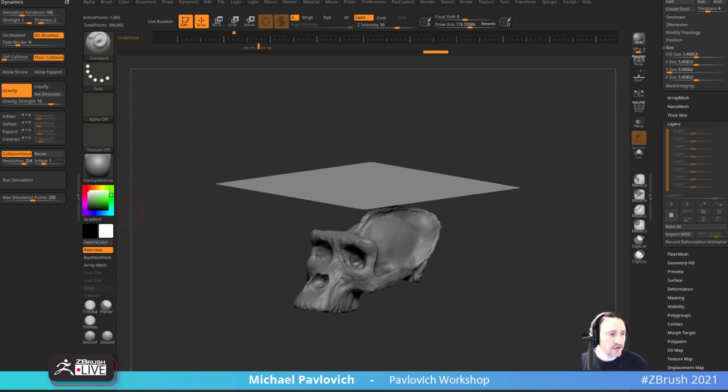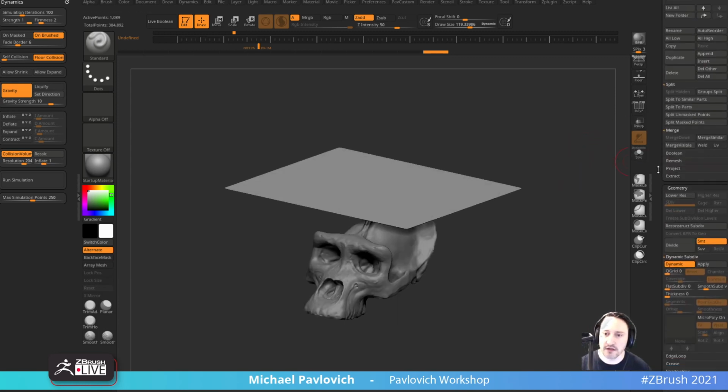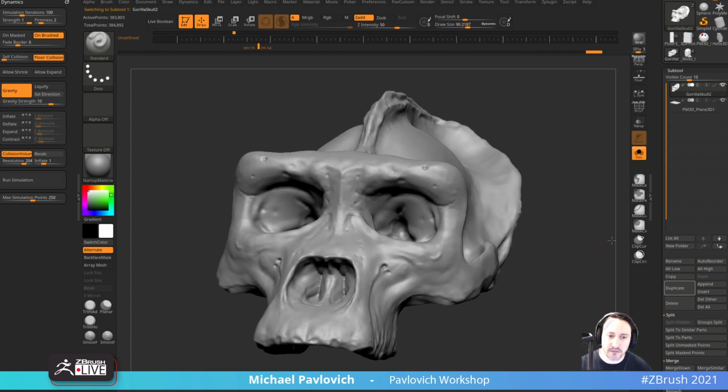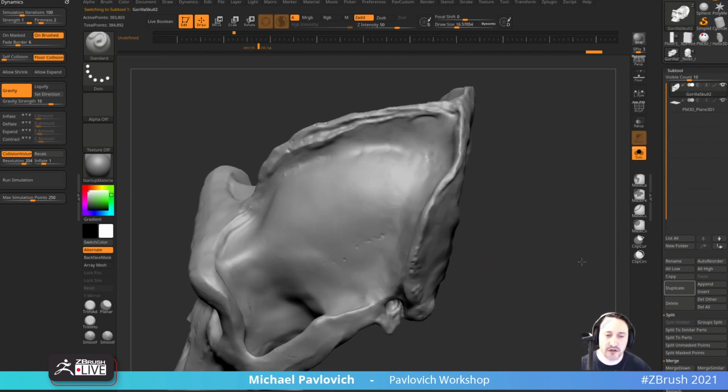Do you have to retopologize your mesh for print? No. Usually just Decimation Master. Now you want to be careful with Decimation Master, because if you have any kind of nasty geometry, if you have anything you need to clean up, like I'm sure there's some on here, but occasionally you'll have geometry that flips and folds over itself.